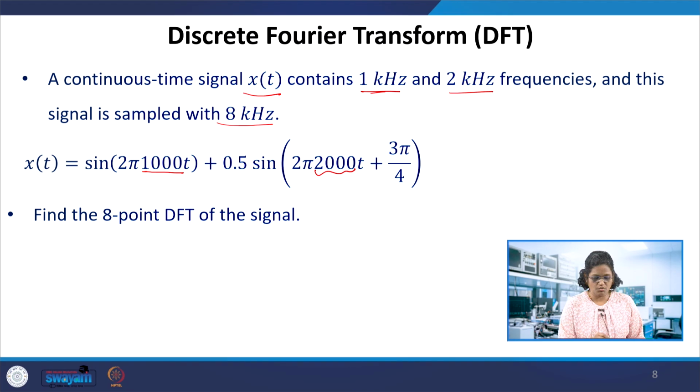So to analyze what frequency components are present, the spectra reveals that information: what frequencies are present in this particular signal, what the amplitude is, as well as the phase of that signal with respect to the fundamental cosine of the signal. So it gives the magnitude, phase information, and the frequency content present in the signal.